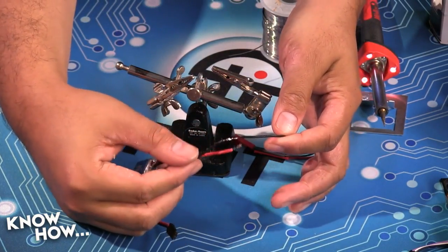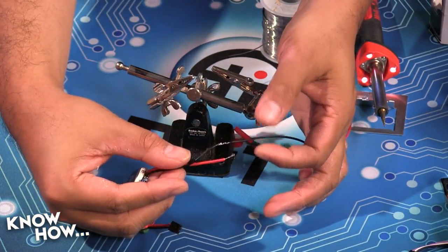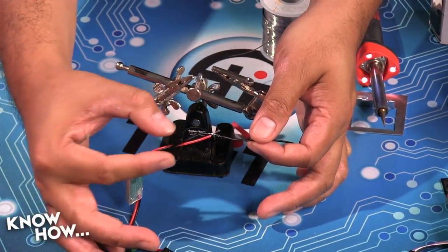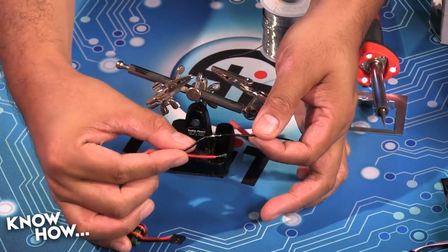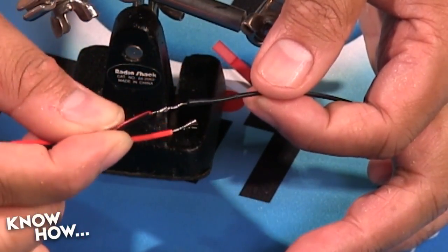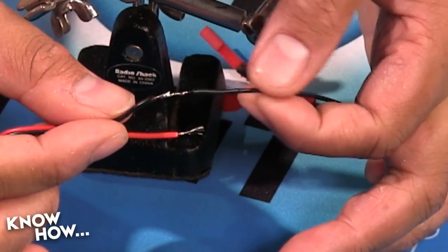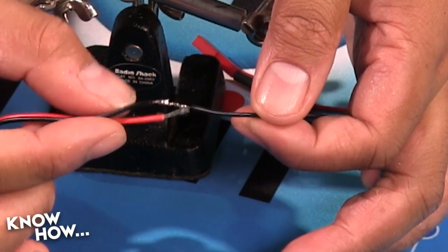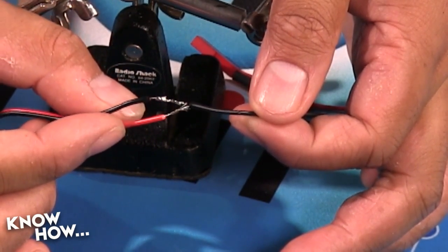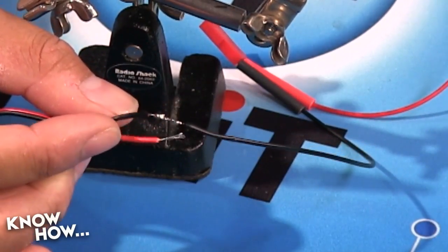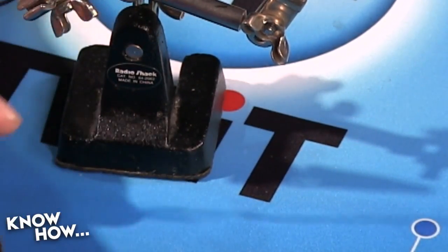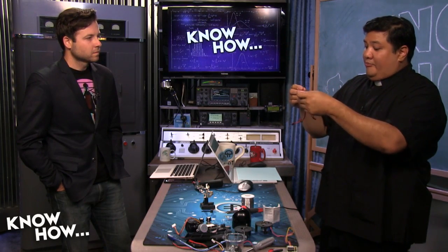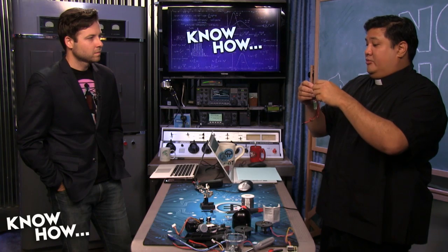Something else a lot of you are going to run into. I've got two different types of wire here. This is silicone, which is nice. It will handle basically any heat that I could throw at it. This is just polyvinyl chloride. You can just feel the difference: the rubbery texture here and the plastic texture here. If you heat up PVC too much, it just burns and melts, so you want to do this quickly. Or if you're going to have an application where you can't do it quickly, you want to make sure that you're using silicone wire all around.